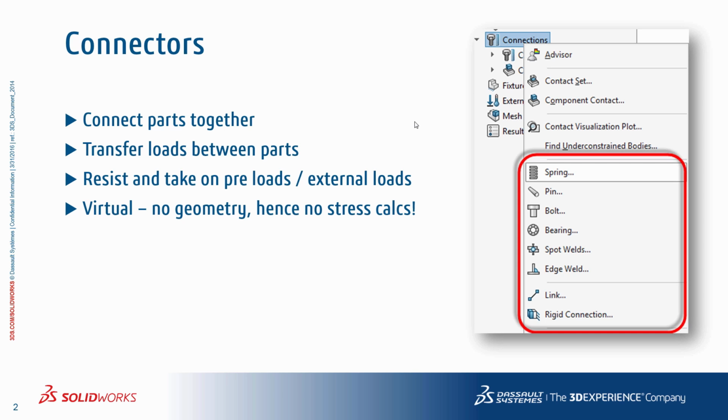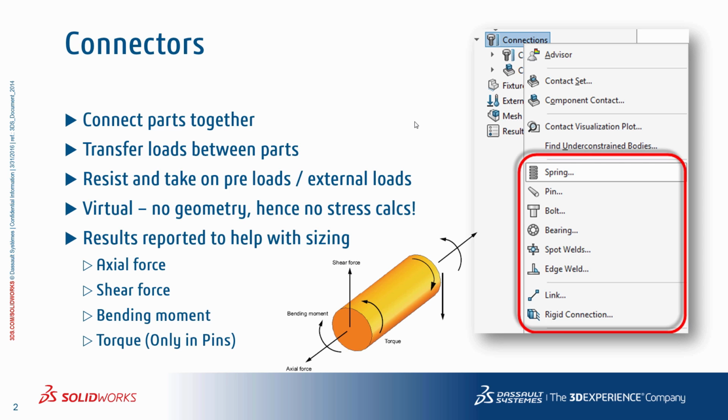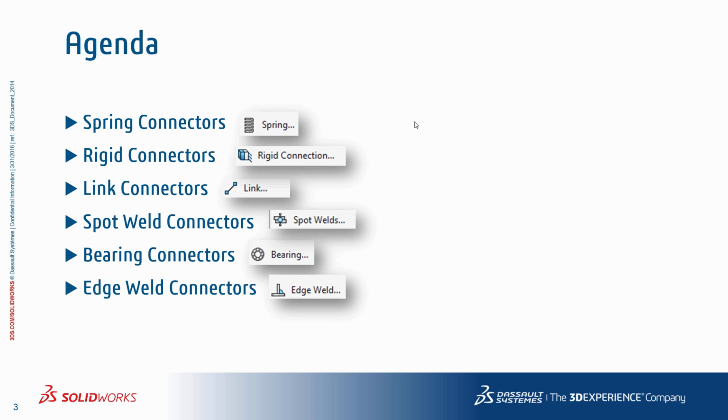Now, all these connectors are virtual, meaning there is no physical geometry required for simulation. Hence, there is no stress calculations available. However, the connectors do report some load results that can help with sizing requirement, such as the axial shear forces, bending moment, and torque.